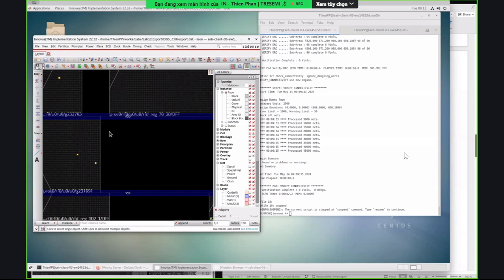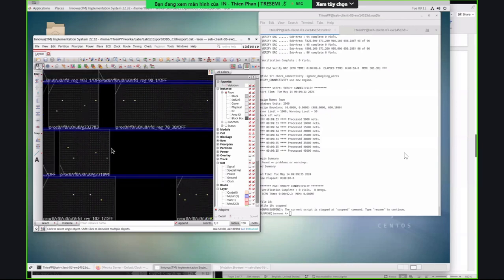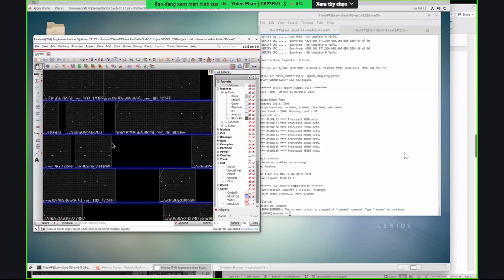That's going to essentially line up with the VDD and VSS of the standard cell, right? And then you have the N-well and the substrate, right? So what's missing here is we have many gaps, right? Without the filler cell, we're going to have gaps in here, right? So the purpose of the filler cell is filling all these gaps, right?